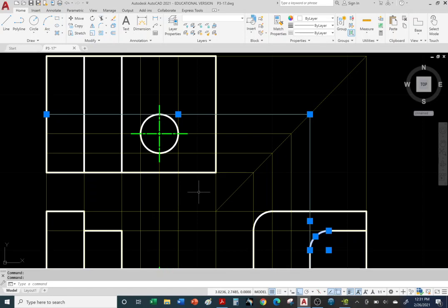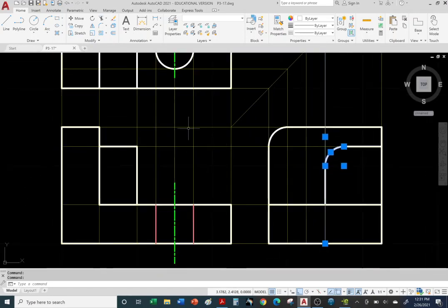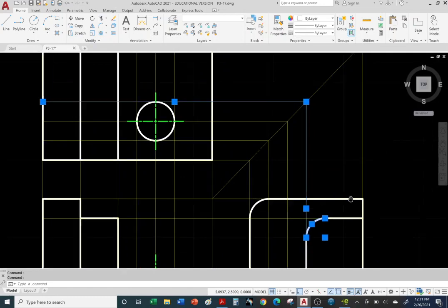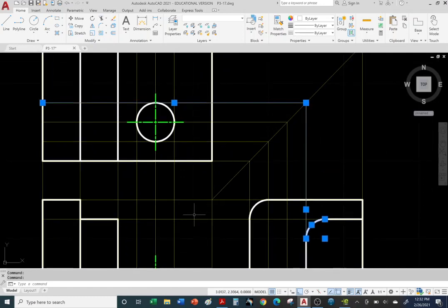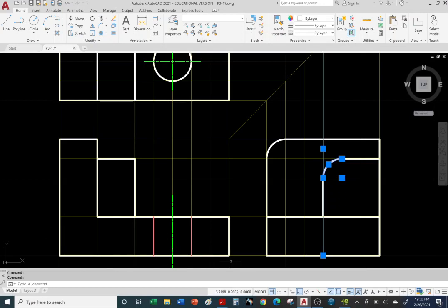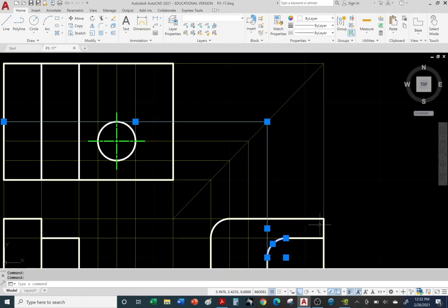Okay, and just a reminder, how did I come up with that 45? Well, when you start doing your own construction lines, you start by drawing a rectangular box around each view before you start drawing. It's just easier when you draw a box. Then you draw a box for this one, right? Then from the corner of the front view box, okay, so this is the front view box, from this corner, you draw a 45. And then from the right side view, you go straight up, hit the 45, go across to then create this box, right? So from the right side view, once again, you go straight up, hit the 45 and across. So that guarantees everything is lining up.